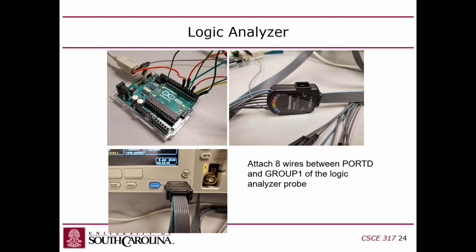So I hooked up a logic analyzer that we're going to have in the lab. Each lab station has a logic analyzer, or actually has an oscilloscope that has an internal logic analyzer. And so what is a logic analyzer? It's a way that you can read binary data in parallel buses. So there's these probes that have eight wires coming out of them.